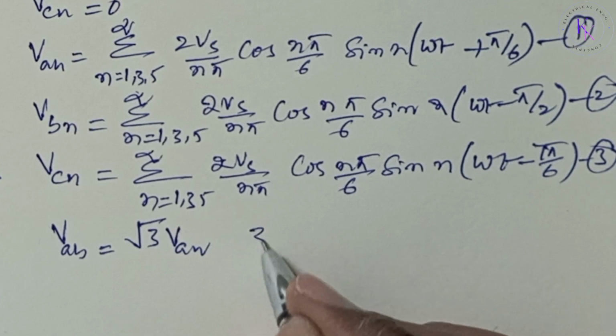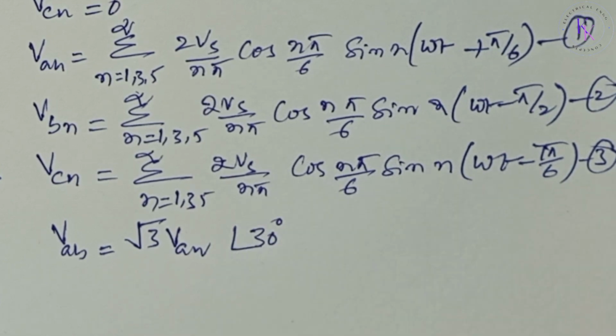of 30 degrees. There is a delay of pi by 6 between the turning off of Q1 and Q4. Thus, there should be no short circuit of the DC supply through one upper and one lower transistor. At any time, two load terminals are connected to the DC supply and the third one remains open. The potential of this open terminal will depend on the load characteristics and would be unpredictable.